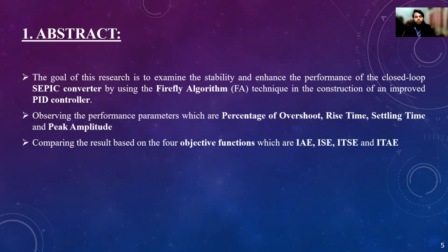The goal of this research is to examine the stability and enhance the performance of closed-loop SEPIC converter by using the Firefly algorithm technique in the construction of an improved PID controller. Observing the performance parameters, which is percentage of overshoot, rise time, settling time, and peak amplitude, comparing the result based on the four objective functions, which are IAE, ISE, ITAE, and ITSE.